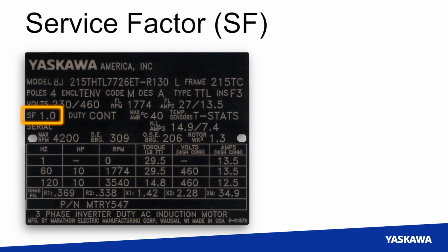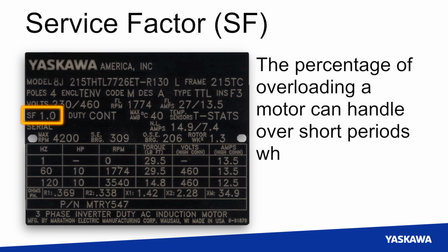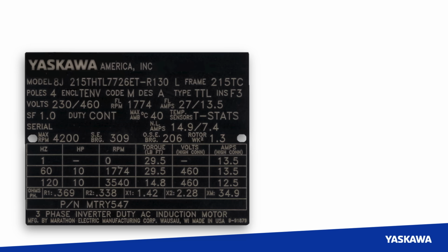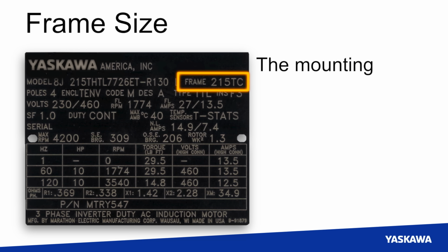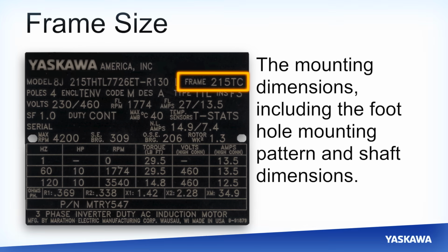Service factor represents the percentage of overloading a motor can handle over short periods when operating at rated voltage and frequency. The frame size describes the mounting dimensions, including the foot-hole mounting pattern and shaft dimensions.